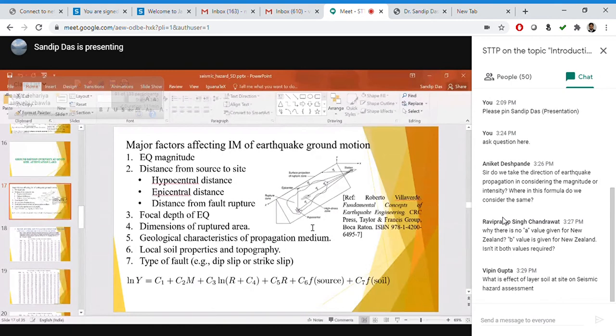But in general we don't consider a radius of more than, let's say, 250, 300, or at the most 400 kilometers from the site. Assuming the magnitude will not exceed 7.5 at most, if it happens far away, beyond 400 kilometers, then as per the attenuation law, whatever ground motion shaking you feel at the site is not going to pose any threat.